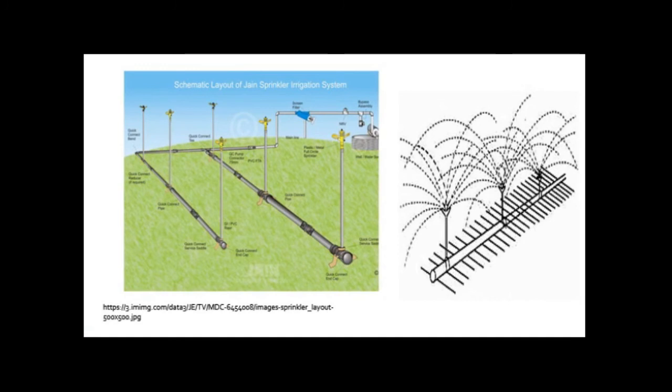Now, the various advantages of the sprinkler irrigation system are that it provides protection to small plants from wind damage and soil from blowing. Likewise, it provides protection against freezing injury to crops, and it is most successful against radiation frost. Likewise, sprinklers can control the soil temperature during periods of high incoming radiation. Soil temperature can rise up to 20 degrees Celsius above the ambient air temperature.